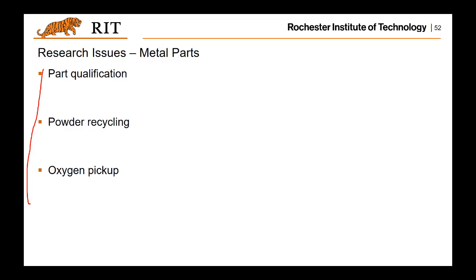And oxygen, right? For both processes, how to avoid oxidization is really troublesome, and there are plenty of efforts devoted to avoiding oxidization and realizing an oxygen-free environment during the printing process, especially for EBM with titanium, right?